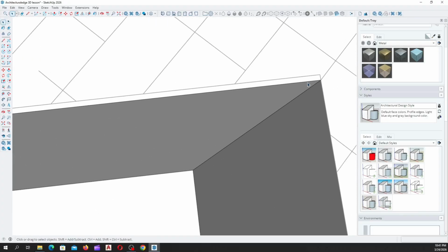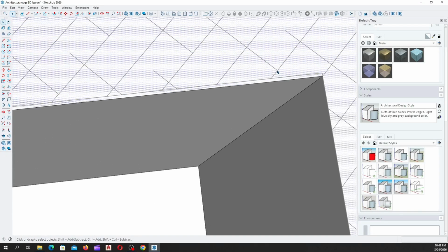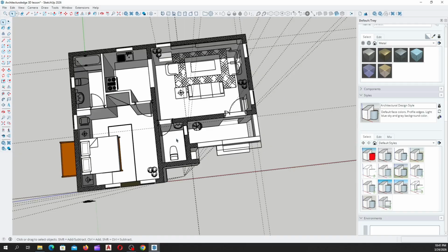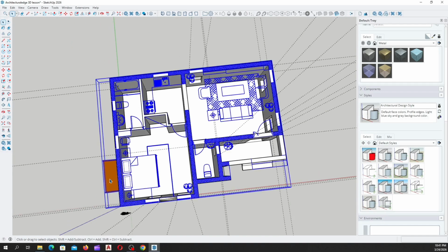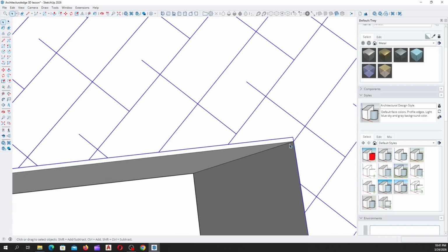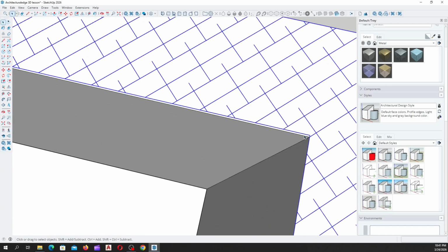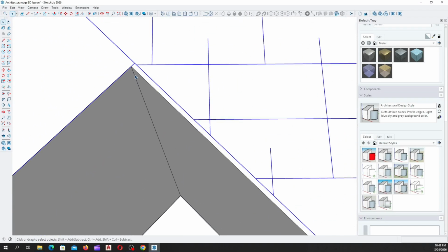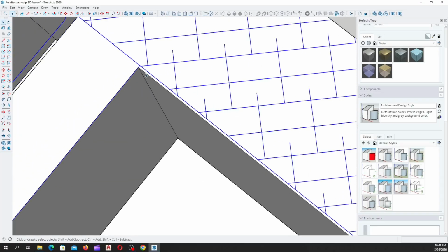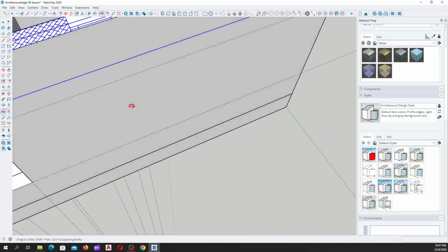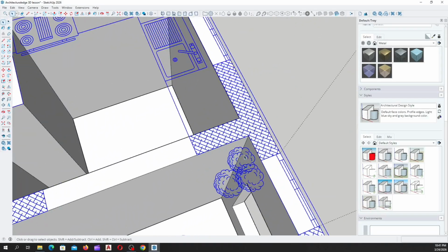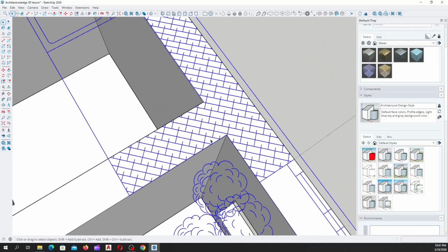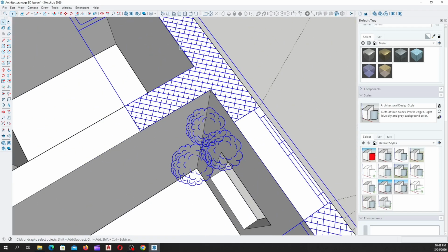If you look closely here, this is where the fault is coming from. This is our floor plan. Let me select the floor plan. If we zoom in closely, as we can see, this wall, when we were mapping out our interior spaces, I didn't snap this properly on the floor plan. That was why when I offset and when I pushed in our window, the thickness of the wall is more than the previous one. If you see, there's a projection here more than this other wall here. So that's why the window is not pushing through.